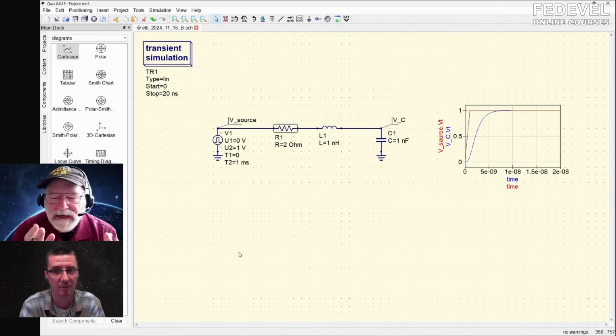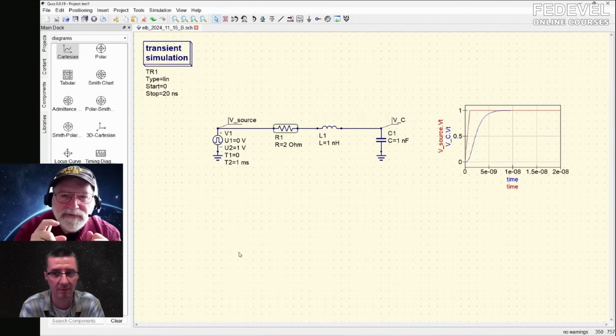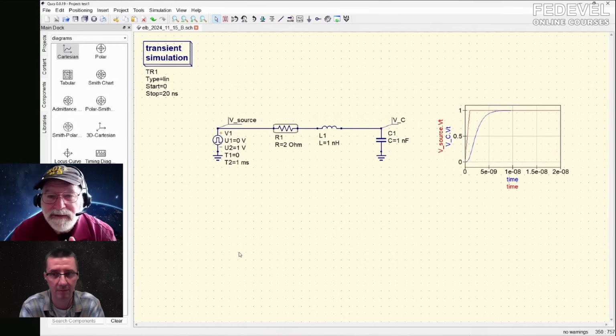So here's how we do that. This is a feature in every version of Spice. We can build an impedance analyzer really easily. The way we do that is we use a constant AC current source, because the definition of impedance is equal to V over I. That's what we're going to control. We're going to make I equal to 1 amp amplitude. That means that when we simulate our circuit, the impedance is literally the voltage.